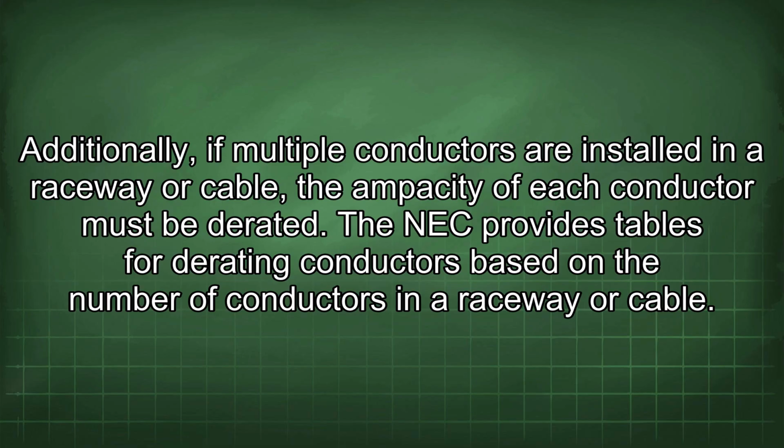Additionally, if multiple conductors are installed in a raceway or cable, the ampacity of each conductor must be derated. The NEC provides tables for derating conductors based on the number of conductors in a raceway or cable.